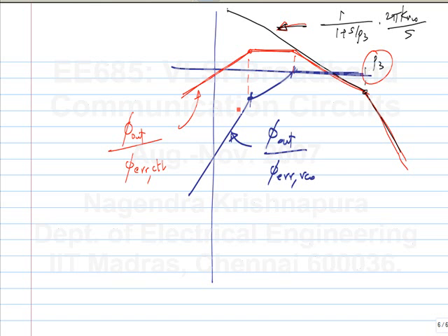Now this is not a very complicated method, it's just keeping track of where the poles and zeros are, and if you know how to sketch the magnitude of the loop gain L, you should be able to do the rest easily. And when you have more complicated systems, such as an op-amp or a complicated op-amp, you can use similar techniques to compute the effect of different noise sources and all kinds of things.